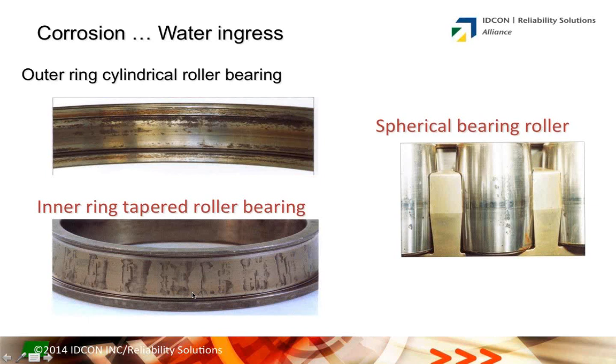What this tells me is this machine actually was contaminated in a stationary condition twice. So this was probably a machine that was installed, left sitting, got wet, got corroded, ran, came back a few months later, stopped, sat, got wet. So there's been two events where it got corroded in this particular case. A longer term problem, not a short term problem.